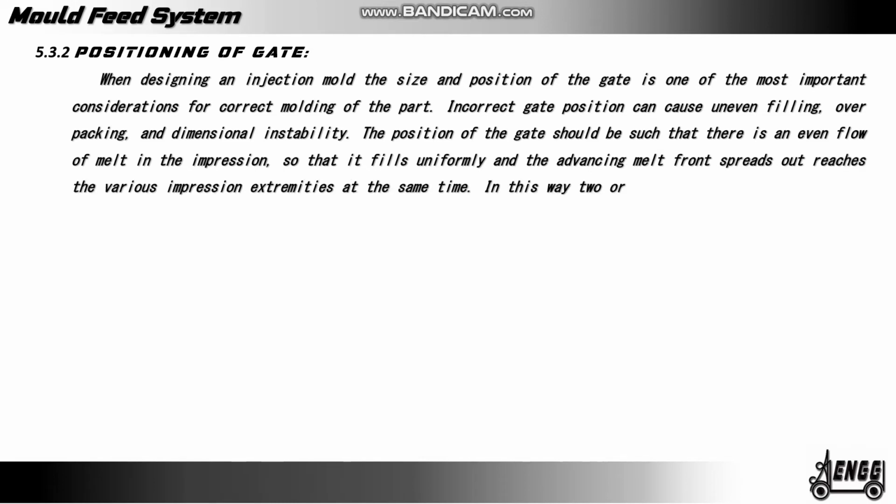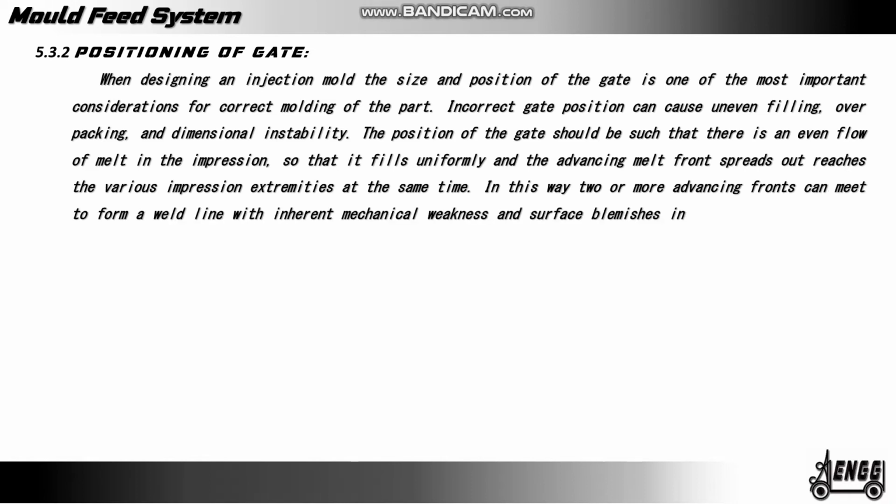Otherwise, two or more advancing fronts can meet to form a weld line with inherent mechanical weakness and surface blemishes in the molding.